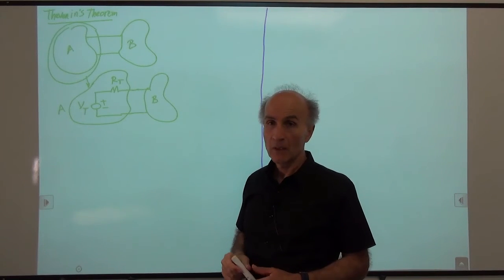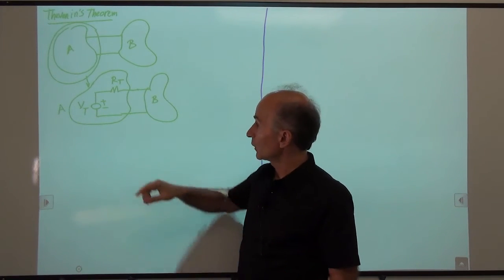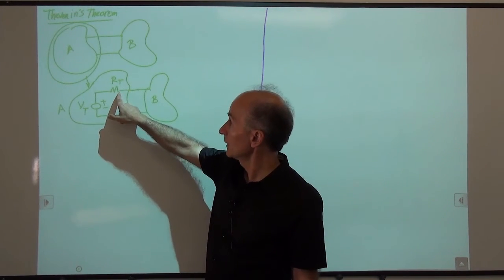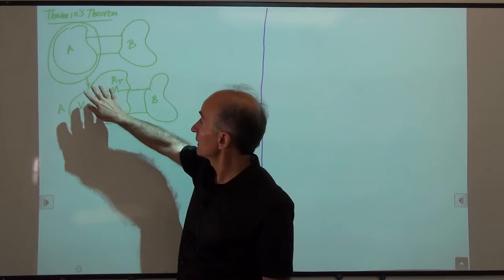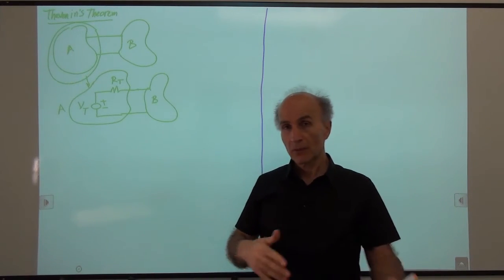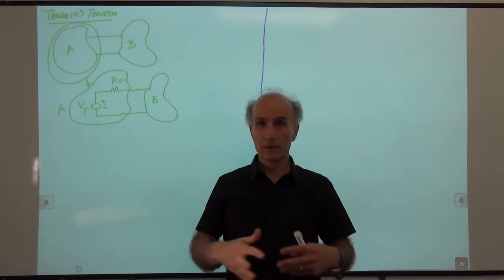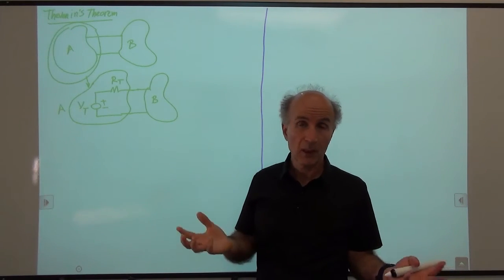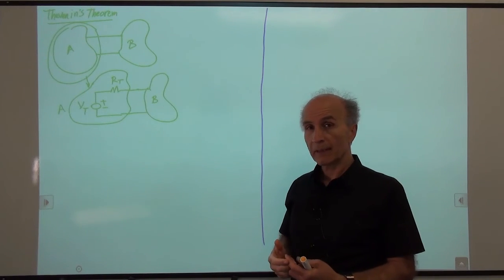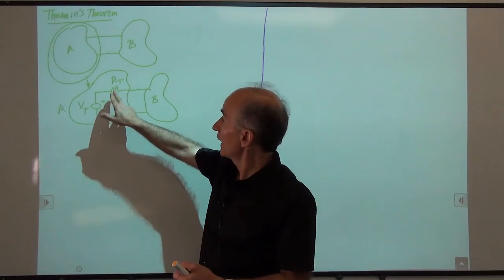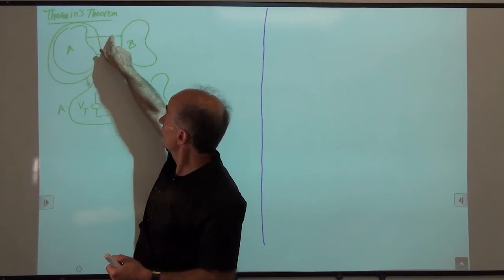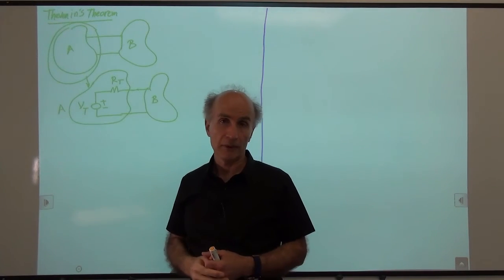So the only question is, how do I find this voltage and how do I find this resistor, which together represent whatever the circuit does, right? The circuit could have dependent sources, independent sources, various devices, etc. It can be pretty complicated, and we need a procedure so that we can calculate VT and RT for any given circuit that has only two wires coming out of it.